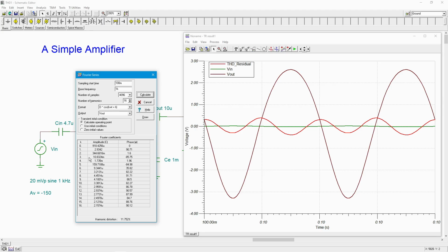Beautiful. Then it goes on and says, well, the third harmonic, which in our case would be 3 kilohertz, is considerably down from that. That's just about 11 millivolts, and it just keeps dropping. All right, and that's, like I said, kind of typical. So we have less than 2 millivolts at 4 times, and then once we hit 5 times, everything is below a millivolt, just microvolts.